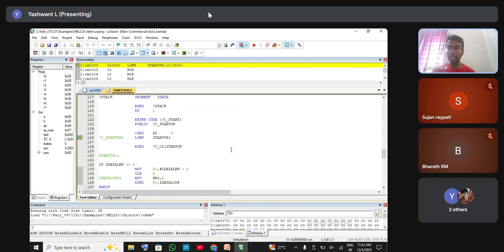Clear the IDATA section. At the top section you can see the register window, which shows all the internal registers of the 8051, R0 to R7, the accumulator, B register, program counter, the stack pointer and the data pointer. These values change as the program executes each instruction. In the assembly view at the top center, you can see the CPU instructions. The yellow highlight indicates the current program counter. Right now the instruction being executed is in the startup file, which jumps to the initialize routine.